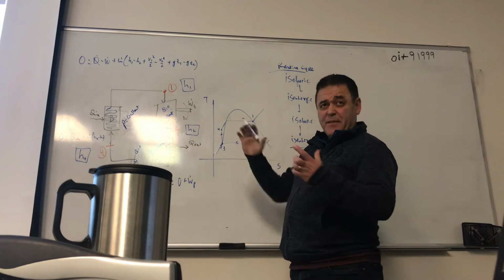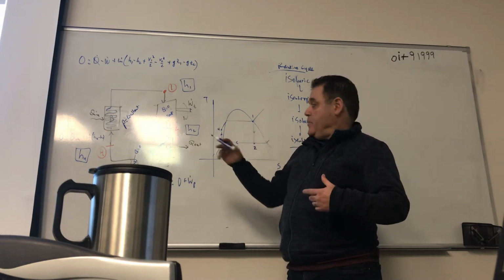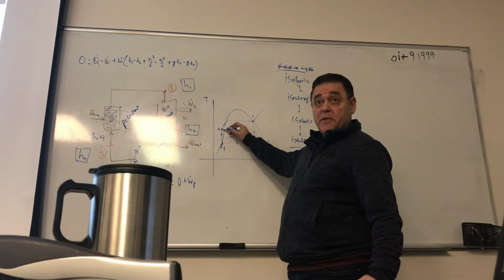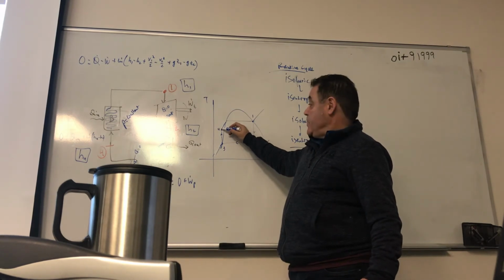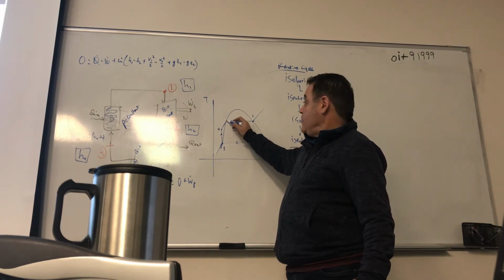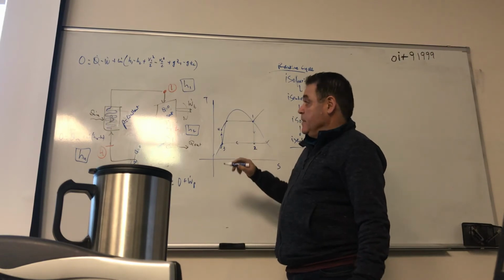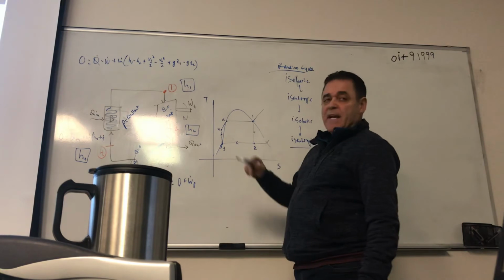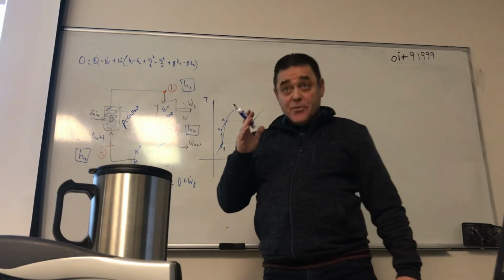Here you have kind of compressed liquid. Now you're adding heat to it. So what's happening? Because it's just liquid, you are increasing the temperature at constant pressure, until I get to this point, which I call point A. What happened at point A? It starts to boil.